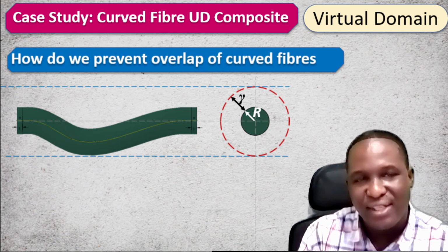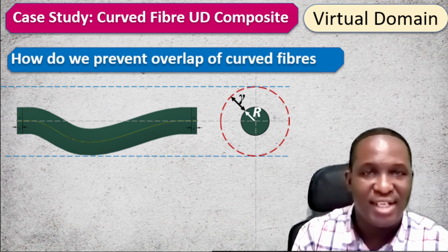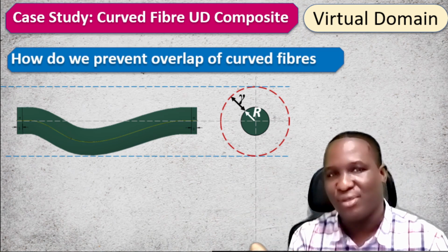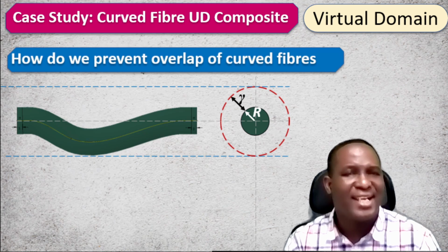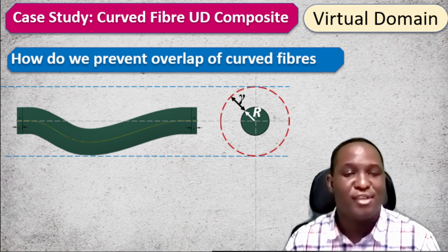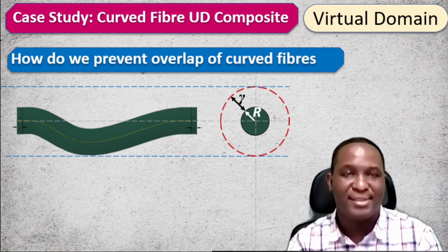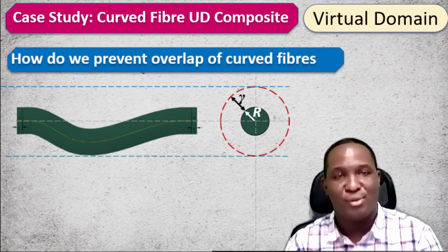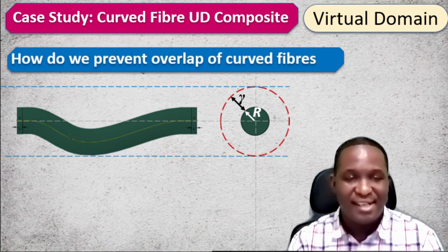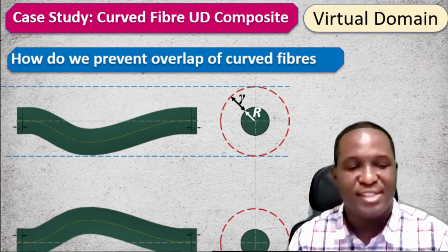So that means we have to find a way to define this gamma value at the time we're trying to create this model, and it will be consistent across the domain. Okay, so this could be in practice maybe related to something like the viscosity of the matrix. The viscosity of the matrix will not allow certain kind of contact between the fibers, because you need to allow for a viscosity effect so that fibers will not come in. So physically, there is a relevance to this gamma value, and we are enforcing that within this domain.